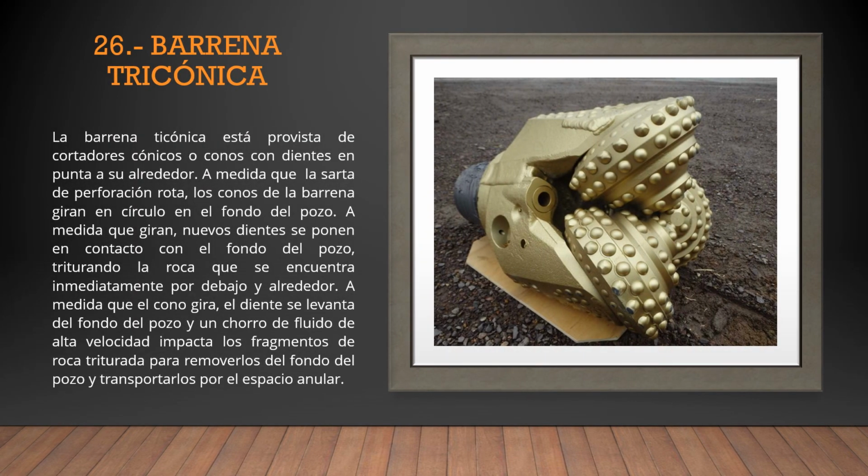With a head that is divided into three main parts. The tricone bit consists of three rotating cones working inside each other and each with its own row of cutting teeth. The tricone bit has three rolling cutter cones with a series of teeth that crush rock as they roll over the rock face.